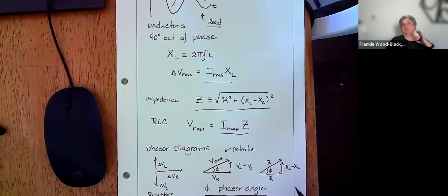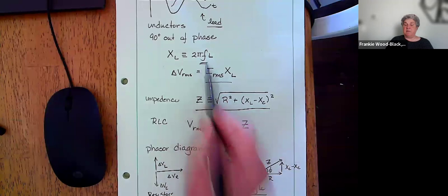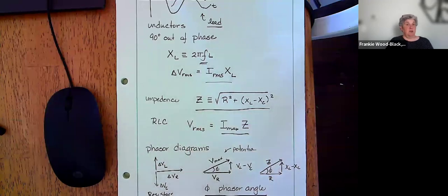Your oven, your electric dryer, big pieces of equipment that require a higher power or higher wattage are probably going to be 3-phase. And you know they're 3-phase because they have a different plug, because that plug is very different, right? Not only that, it's on 220 volts instead of 110, because that's what we use. Now the frequency, if I'm in Europe, is going to be different because it's 50 hertz. In the US, it's 60 hertz. So we have differences there in terms of grid.